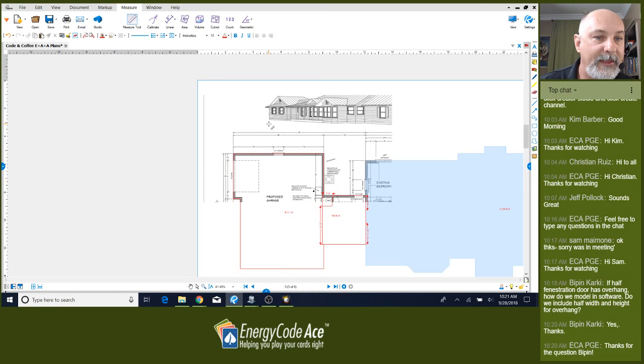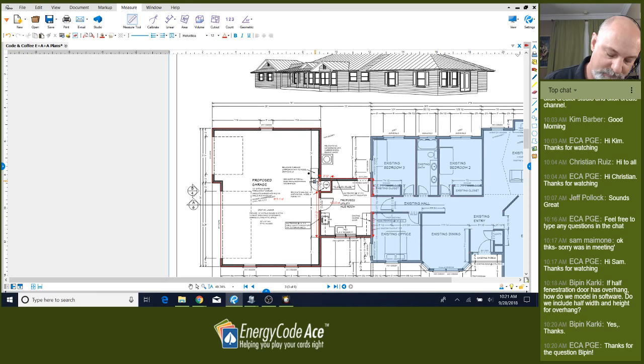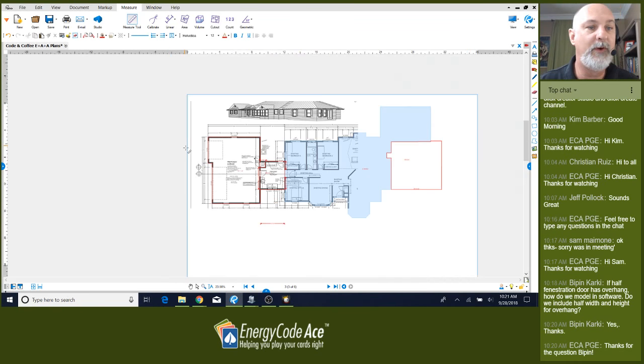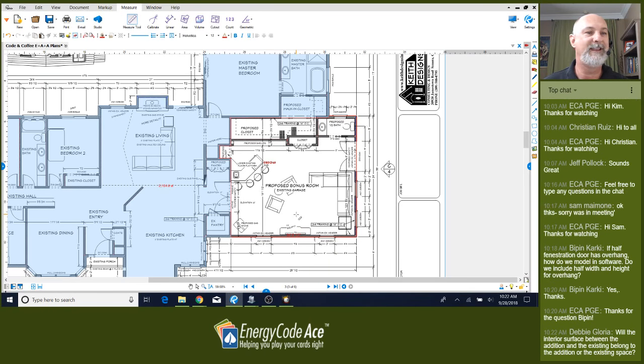And then I do have these returns. I have two right walls, so 7 feet and 12 feet. That is 19 feet times 8 foot is 152 square feet. No windows, no doors. So we're good to go. Let's move on, finish our takeoff, and complete this proposed bonus room. So all of these are going to be on the same floor height, same ceiling height, same floor to floor height. So I'm not going to worry about that right now. When we start modeling, I'll set all that.